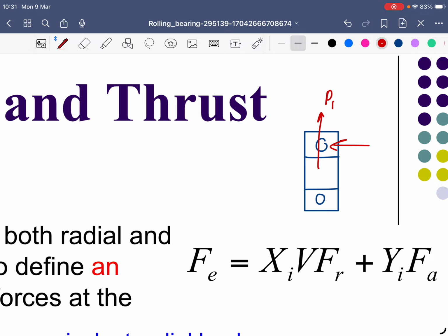But if now this gear is a helical gear, you have the load this one and this one. Because the push of the helical gear is something like this. So then this load will create what? The side load this way to the bearing. So now the bearing supports the axial load and radial load. You support this load.